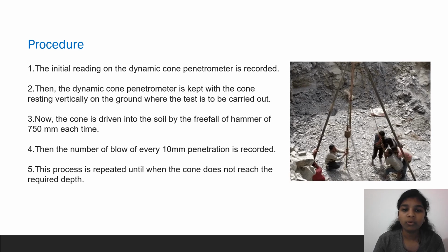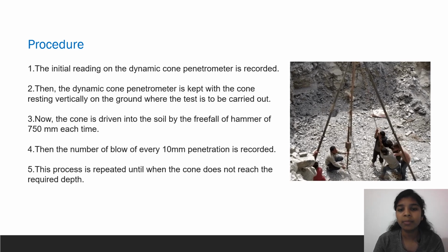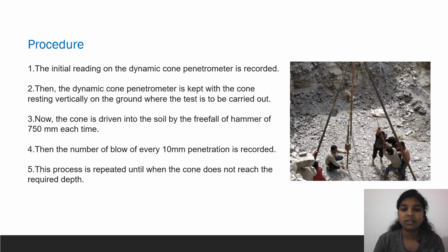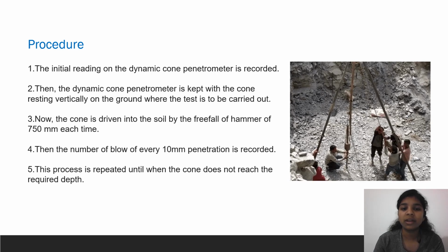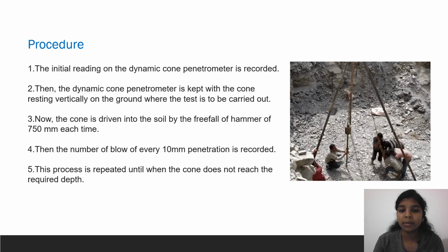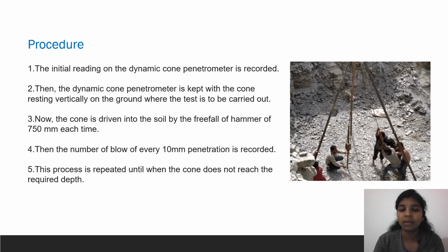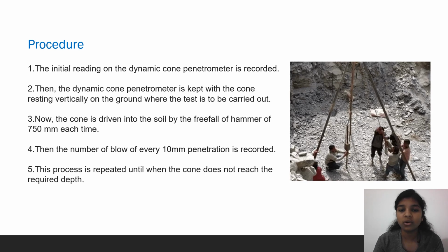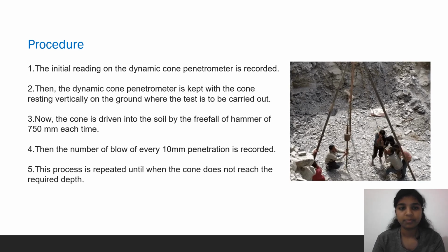Then the number of blows for every 10 mm of penetration is recorded. For every 10 mm depth, the penetration is recorded. This process is repeated until the cone reaches the required depth.